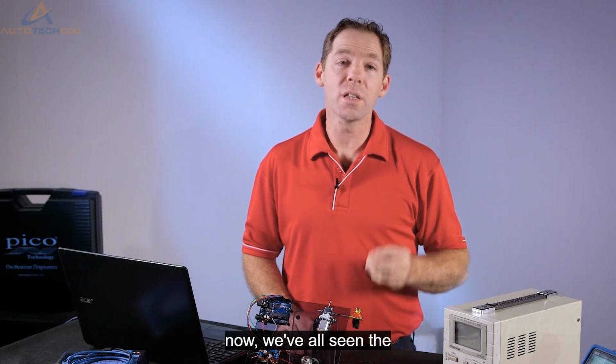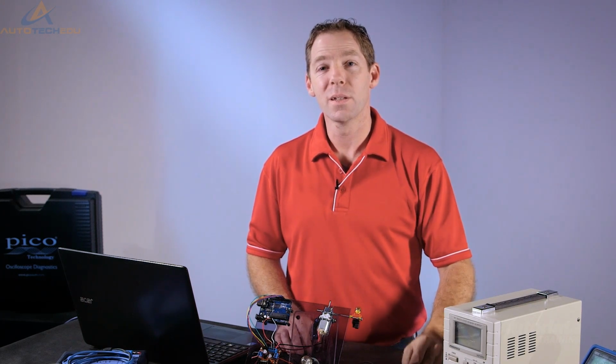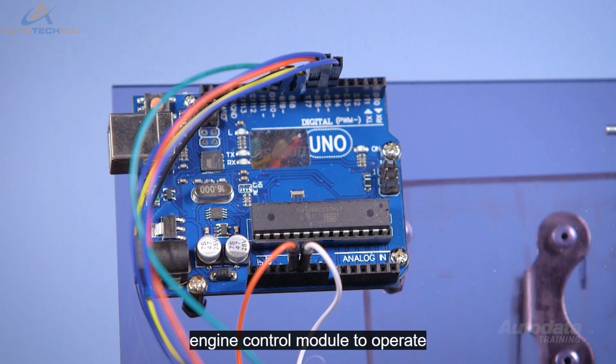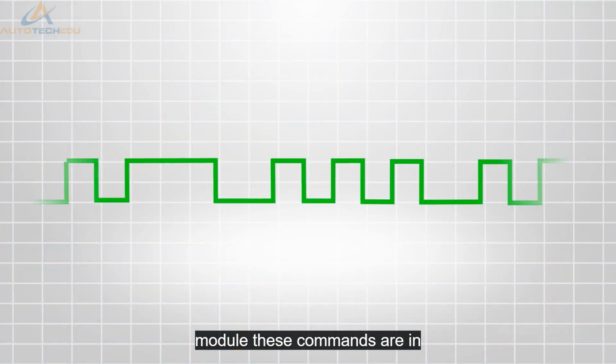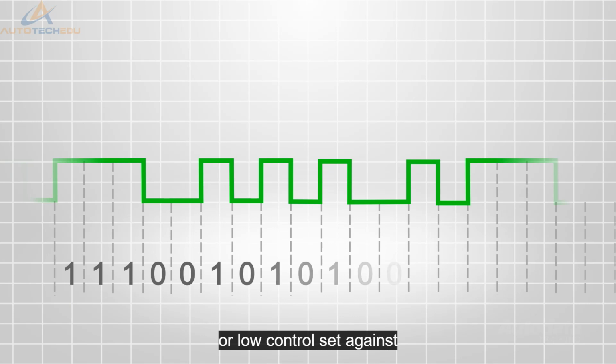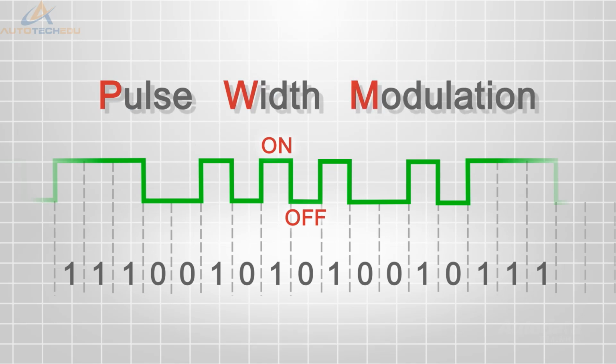Now, we've all seen the effects of PWM control in electromechanical actuators. But do we really understand how it works? For an engine control module to operate an actuator, it first generates a command from the central processing unit. I'll be using this microprocessor to simulate a control module. These commands are in the form of a high or low control set against a time base. This on-off or digital control is pulse width modulation.